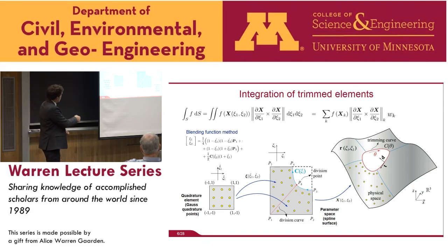What we know is the parameter space of the spline surface. And the interesting thing there is, of course, how to deal with the cut elements. So here we have one of those cut elements. What we can get from the CAD data structure is any cut spline element together with this trimming curve in the parametric domain of the spline. Now, we know that Gauss quadrature is defined in uncut elements. So in order to integrate this accurately, we define new so-called quadrature elements that we can map forward to the cut spline element in such a way that we can parameterize this accurately.